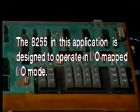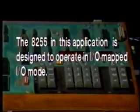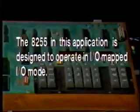The 8255 in this application is designed to operate in I/O mapped I/O mode. The I/O address of the control word register is 23H.